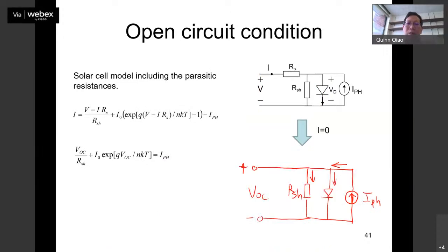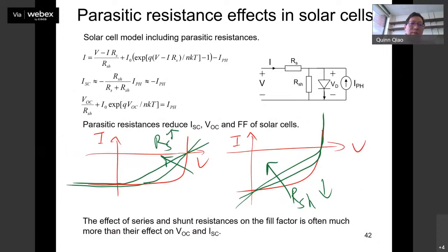And then the same thing you can analyze for open circuit conditions, right? Under open circuit, there's no current flowing here, so you can get rid of this part, right? So now the current flows, some through the diode, some through RSH, okay? And then you can see this IPH, this is the total, right? Under open circuit, it will be ISH plus ID. This IPH is equal to what? Because this total current, some goes to ID, some goes to ISH, right? ISH plus ID equals IPH, right? This part plus that equals that, okay? So that's about the shunt resistance and series resistance.